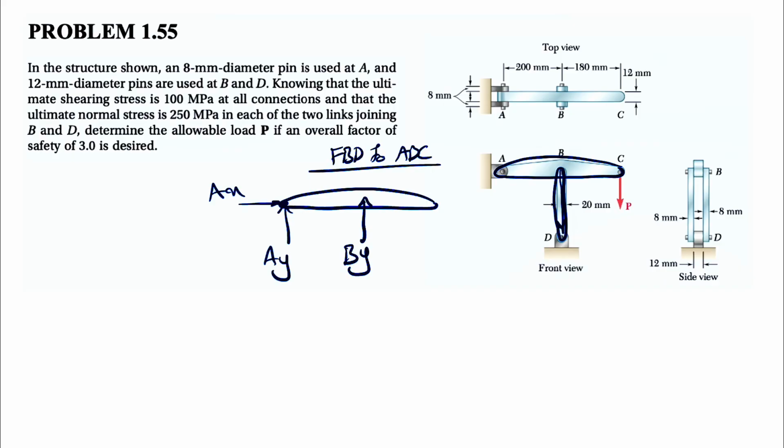So it's either like that or in the opposite direction. So we know the force applied from the link to this joint is in the Y direction. That's why I don't consider any X component here, and again it comes from the concept of a two force member.